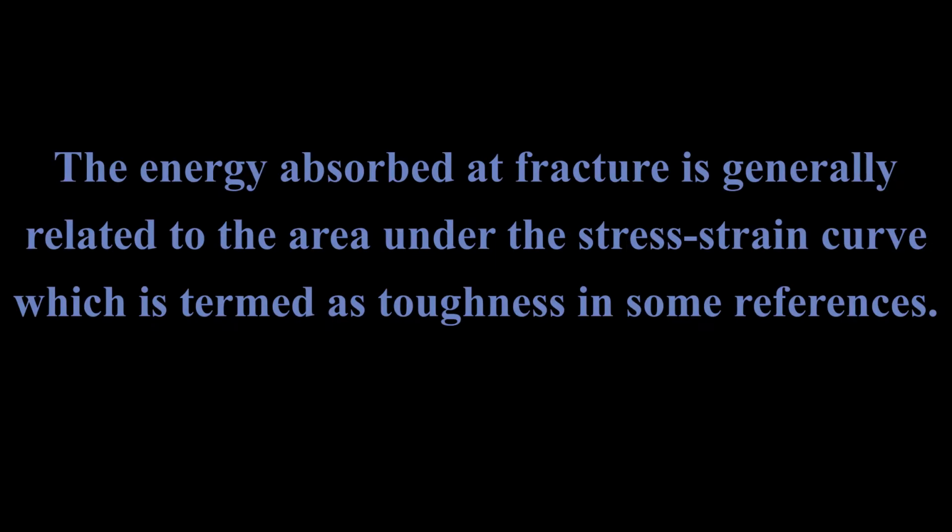The objective of this experiment is to conduct an instrumented Charpy V-notch impact test and determine the Charpy impact resistance of engineering materials. Notched bar impact testing of materials provides information on failure mode under high-velocity loading conditions, leading to sudden fracture where a sharp stress raiser, a notch, is present.